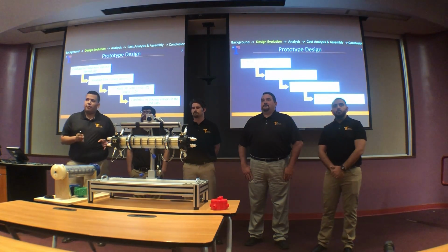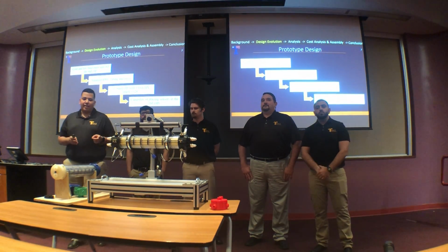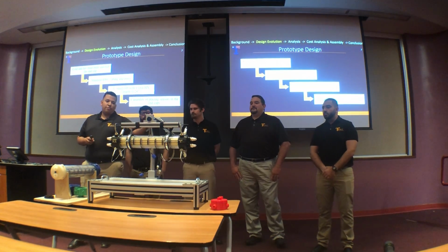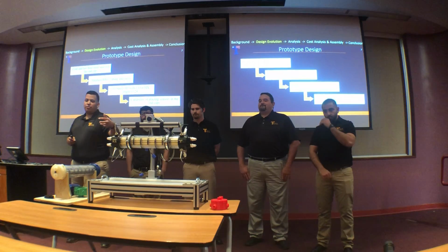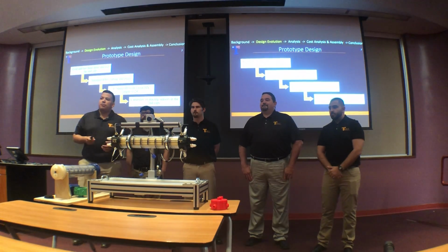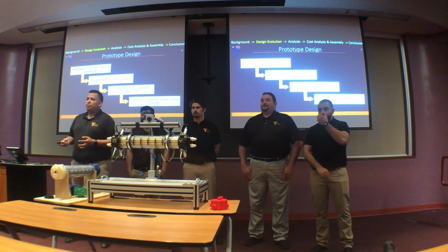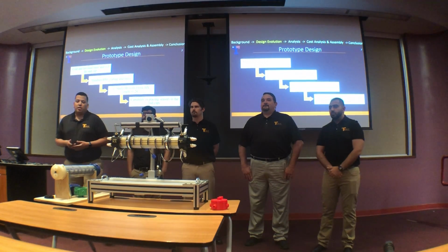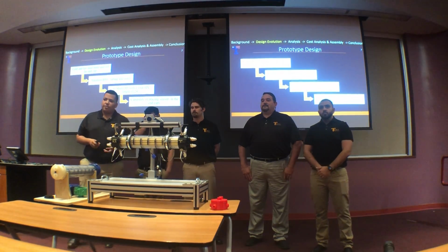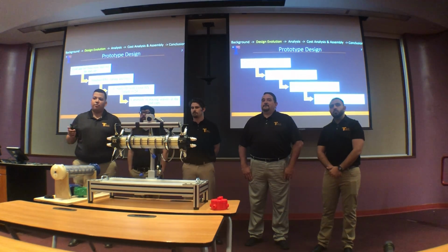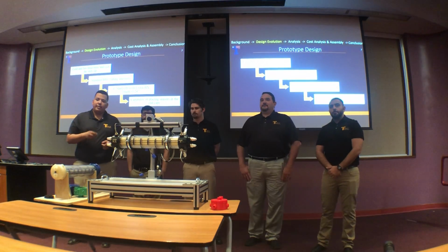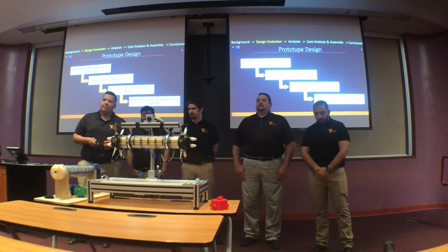minute. Our prototype design consisted of the end caps where the hot fluid and cold fluid will be entering the end cap and getting out through the other side of the end cap. So our standard tubing is BWG tubing with a triangular pitch. Our outer diameter of the shell is 4 inches, and our total length is 24 inches. The end caps have sensor capability at the ends.